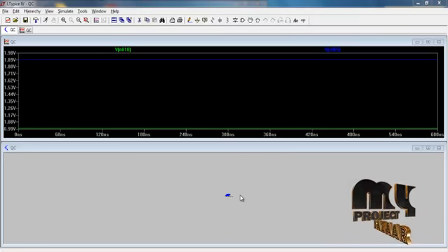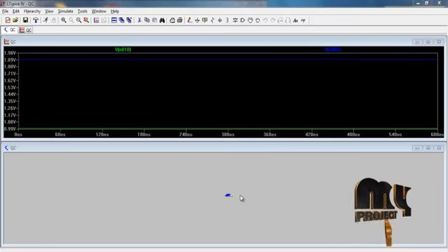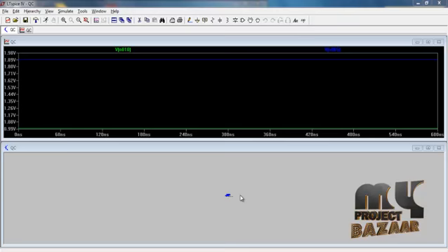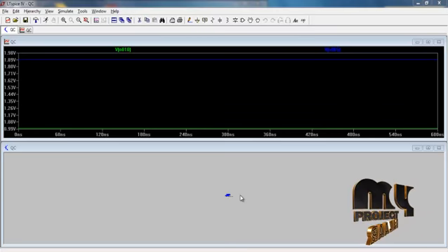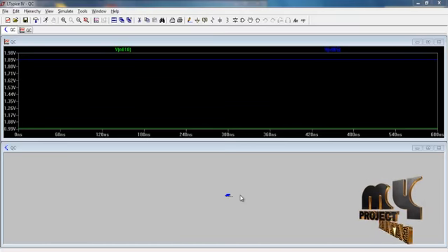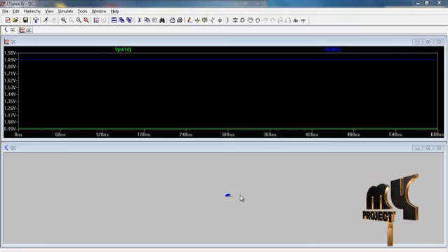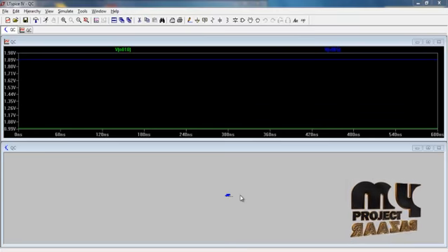The type 1 BTN does not provide the function of a quasi-circulator. A 3-port circulator could also be achieved using the bridge-T networks. The output is based on the output from the RF resistors. The significant notch response of S31 is attributed to the bridge-T network and the internal inductor, and low S13 is mainly affected by the feedback resistor.